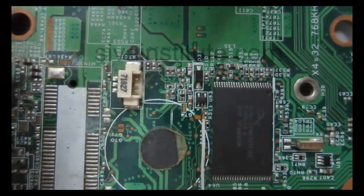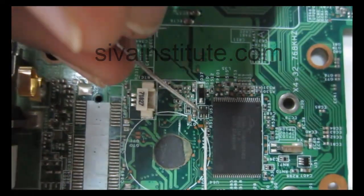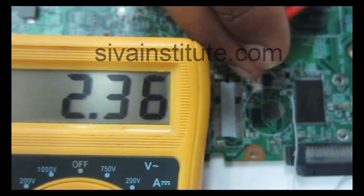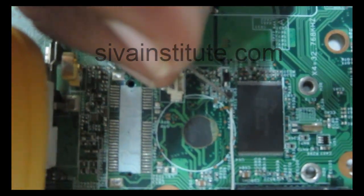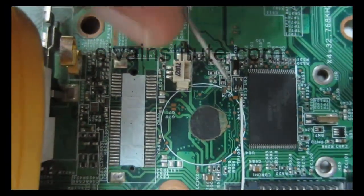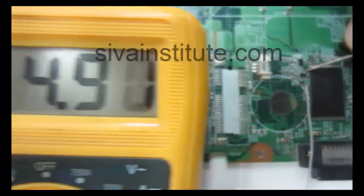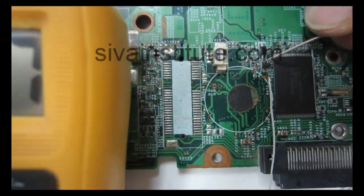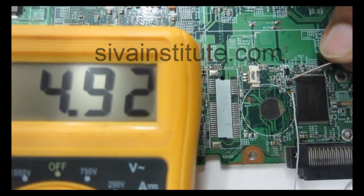This is the U63 5 pin IC. We will check without the SPI command. Pin number 1: 2.3, nearly 3 volts. Pin number 2: no voltage. Pin number 3: no voltage. Pin number 4: 4.9 volts. Pin number 5: 4.9 volts. We will give the SPI command.